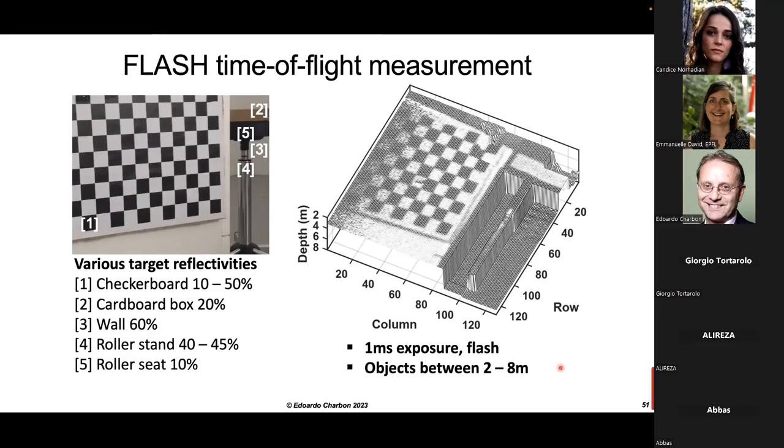As for the V, voltage variations, yes, these are concerned. So again, for the digital section, there's very little variation because the signal being digital, it's very resilient to variations in VDD, as you know. But variations in excess bias voltage, which is the voltage in excess to the breakdown voltage that is used for the SPAD, will change the sensitivity by a bit, a few percentage.